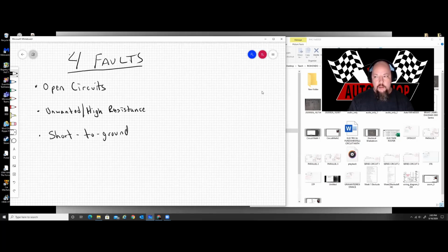That being said, if you had a wire that's contacting ground after the light, it just acts as another ground. Okay, and the only problem you run into is more of a long-term problem with wire integrity and corrosion and things like that, which can present other problems. For right now, we're just going one fault for one reason at one time, so we will stick with the before load for right now. Okay, understand that most of these things do have more to it. This is just going to get you the starting information you need to begin wrenching and what have you.